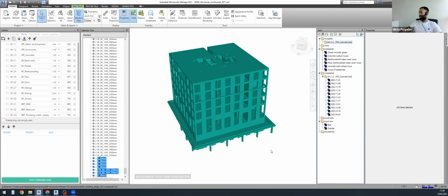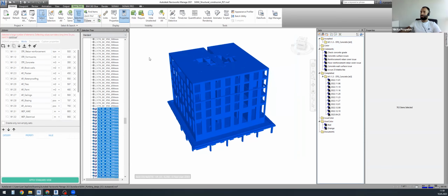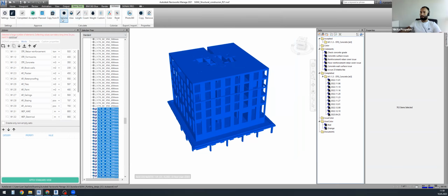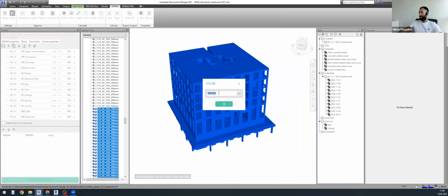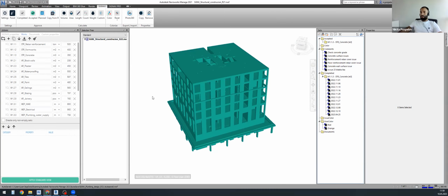Hide. So something like this, using predefined search sets created using SIGNAX tools, we can get the scope of elements we would like to send for the approval to the consultant and get the scope of number of these elements. So 2000 cubic meters, we would like to get paid for this number of the elements. So these were the main features inside SIGNAX tools for Navisworks.